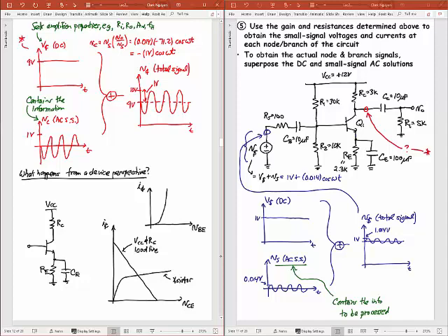14 millivolts is a small signal. But the output, definitely not a small signal. But still, this analysis works, and I'll tell you why in just a second. The total voltage then at this node that I'm pointing at is going to be a 1 volt oscillation around 9 volts, as is shown right there. Okay, so that's what I just did.